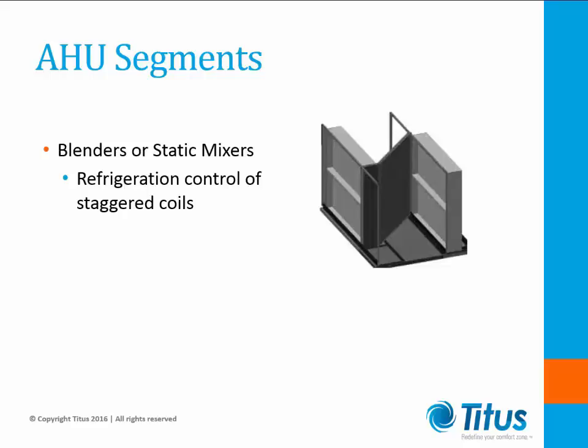Another possible issue with staggered coils is downstream stratified air being pulled into the inlets of a double-wide fan or a multi-fan arrangement, and not properly mixing before being discharged into multiple ducts. This condition could bring bigger issues with control of the unit and comfort problems for those demand areas.